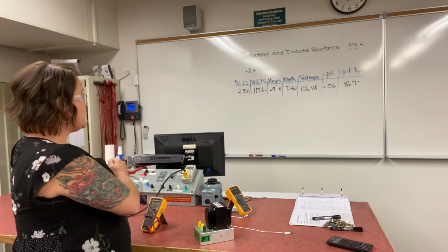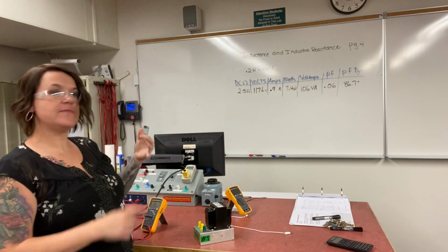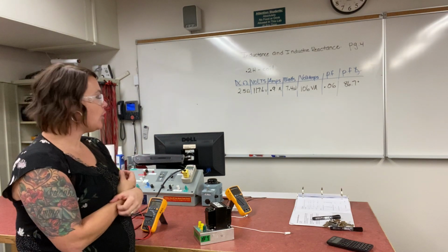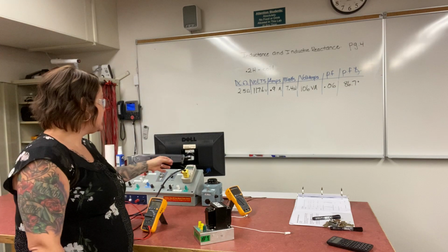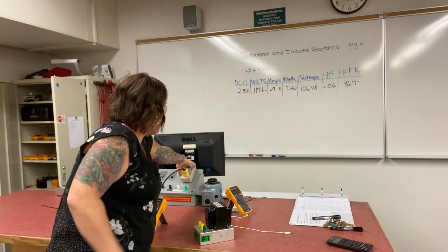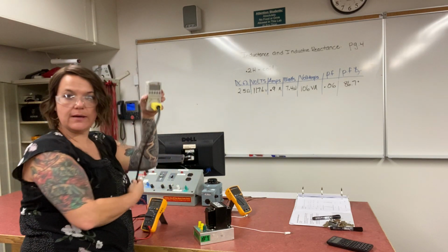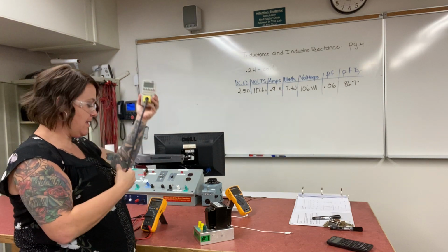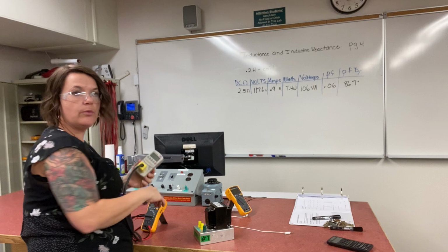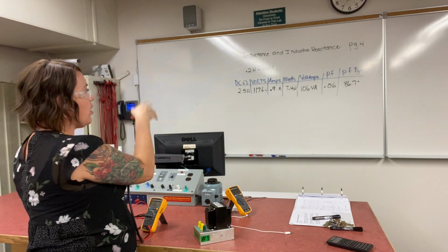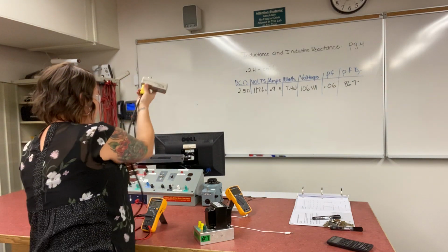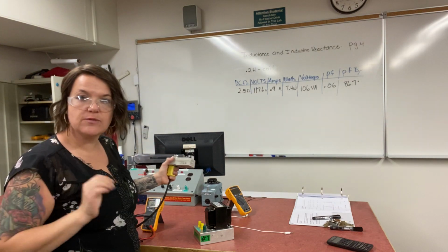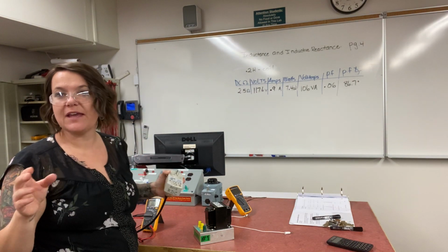The next information that's asked for is the volts, the amps, the watts, the volt amps, the power factor and power factor angle, and all that information is given to me via my kilowatt meter. My kilowatt meter is just plugged into my bench, and using a cheater cord, I will wire my coil and get all of that information and put it into the chart, and then discuss what that means in regards to the expected calculations.